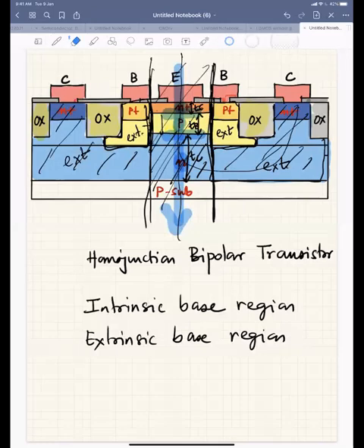These are N. The only thing is when you're taking the contact, you need an ohmic contact. We have not yet discussed ohmic or Schottky contacts. For the ohmic contact, you always have to take contact from the highly doped region, right? So you have N, but you make it N plus so that you could have an ohmic contact. A PN junction is a rectifying device, which means it only carries current in one direction, right?